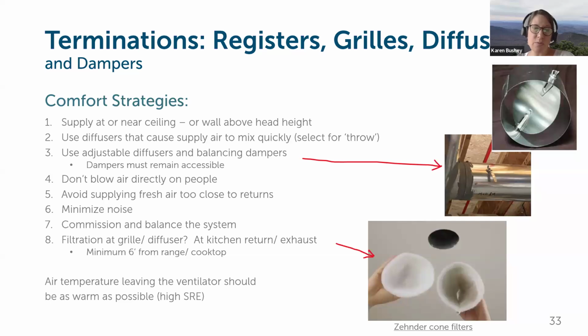But they're pretty porous. I'll throw in, and we talked about this in the last one too, that we want to ventilate kitchens, but an ERV or HRV is not a kitchen exhaust fan. It can't go right over the stove. It can be in the kitchen, but not where you're cooking. And they are not makeup air for any kitchen appliance like a vent hood.